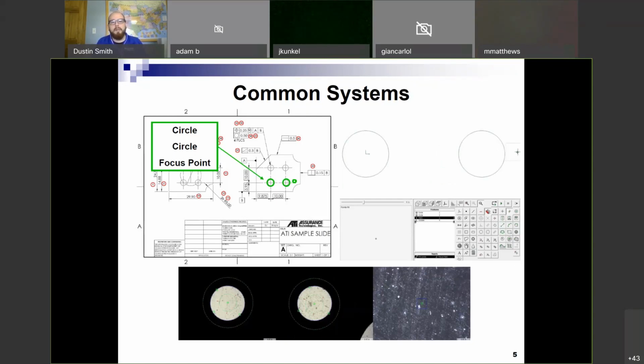So what you could do is measure the two diameters and then click line. When you click those two diameters, it'll create a line between the two center points that you can skew off of. If you want fewer steps, especially if it's a long program, measuring that line and setting that line on there could save you time in programming. So if you're visual, go ahead and click line in the two diameters. If not, you can trust that the skew is between the two diameters there.